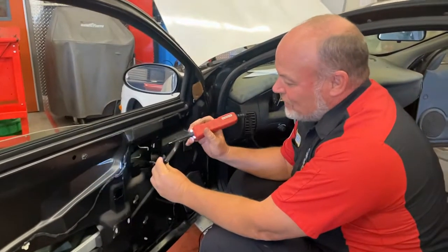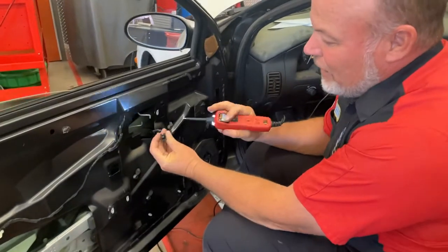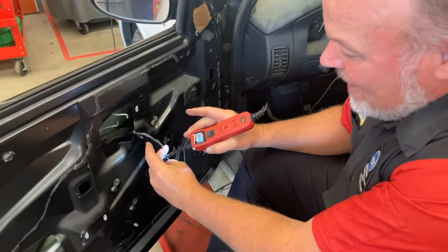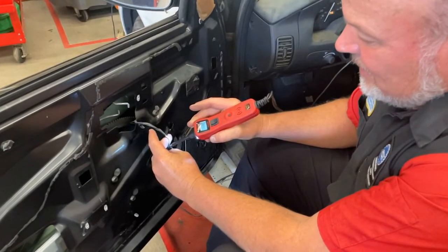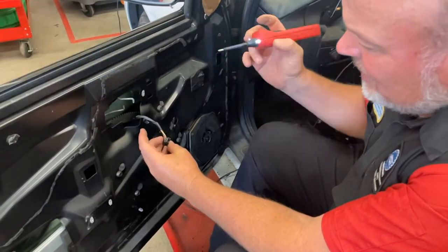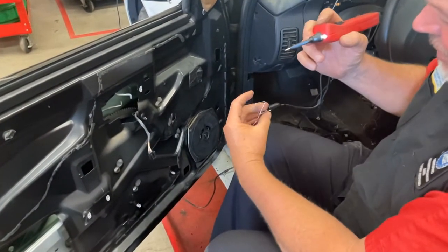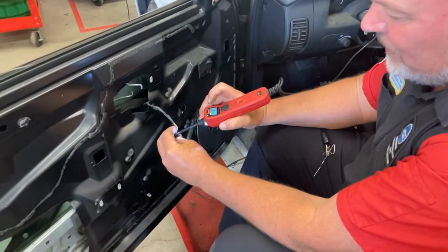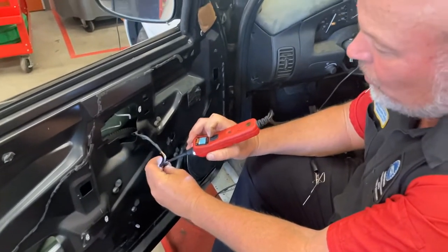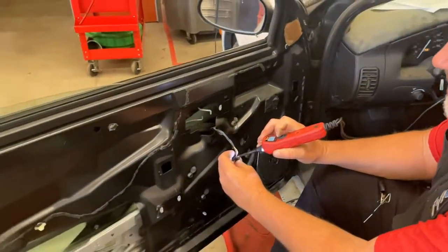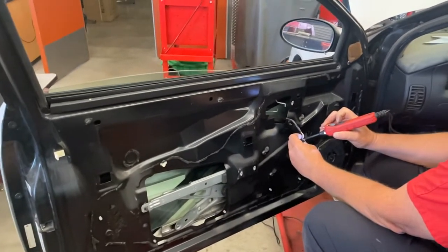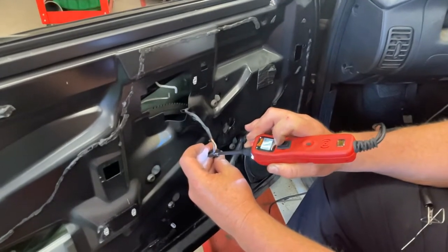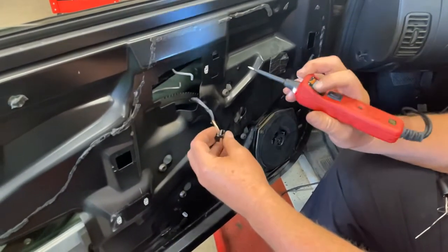I'm just trying to teach you guys a little something extra. So I didn't really put a lot of thought into this. So I need to verify which is which. So that's power and that's ground. So then technically I don't need to back probe this with the paper clip, because when you see ground, that's most likely the wire going to the door lock, and you can see that. So you do not need to attach a ground wire because it's grounded automatically. And you can see how I'm using that power probe to activate that.